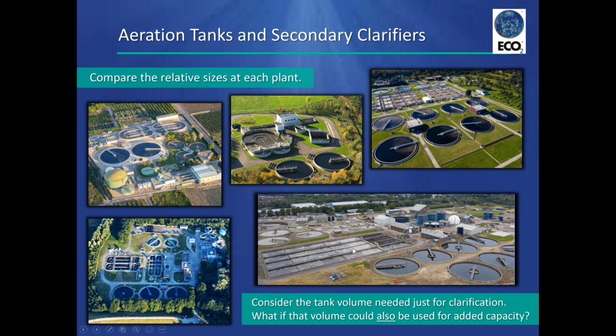But then we note that when we transfer that mixed liquor from the aeration tank and we put that into the secondary clarifier, we essentially have 2 milligrams per liter of DO here, and that rapidly disappears so that the clarifier is essentially devoid of dissolved oxygen. So again, I want to emphasize, notice how quiescent the clarifiers are and how turbulent these are.